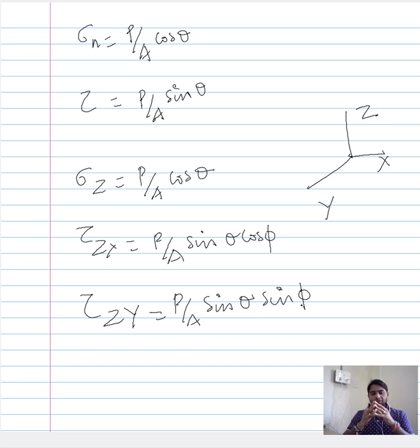So what we have seen so far is that under uni-axial tensile loading, in a two-dimensional system, a region of interest experiences a mechanical condition described by two components of stress. In a three-dimensional system, we have three components of stress describing the mechanical condition experienced by our region of interest.